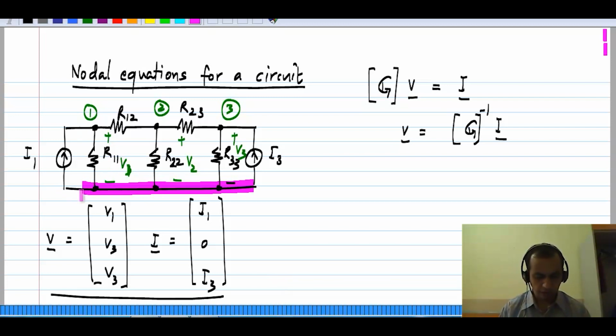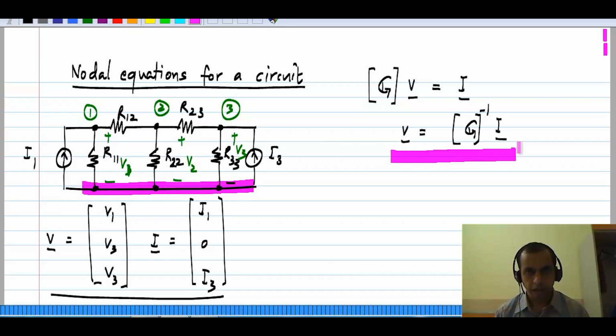We wanted to solve for every voltage and every current. But by doing this, the important part of the work is already done. Then all we have to do is to identify between which nodes each component is connected. That, with the trivial application of Kirchhoff's voltage law, will give us all the voltages. Okay. I'm going to write that down here.